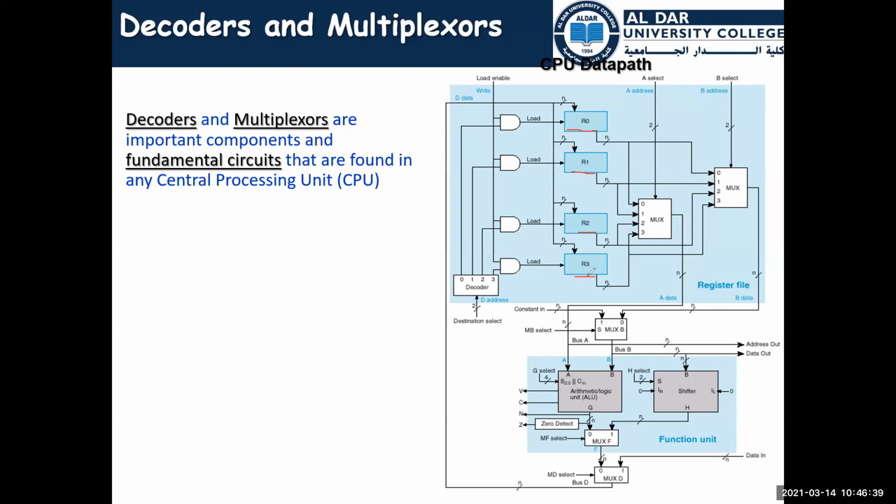And for example, I want to add the contents of this register to that register, to make addition, and pass the result to R0. So I add R0 to R3 and then put the resulting value to R0 again. Okay, this is an example just to show you the meaning of data path.